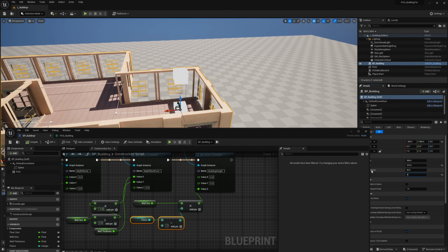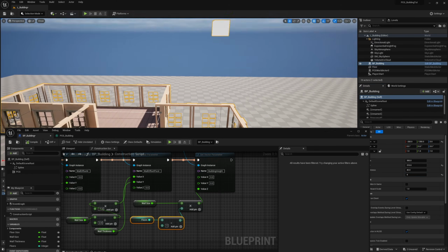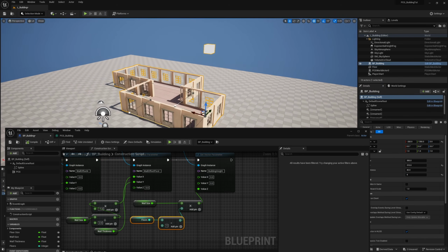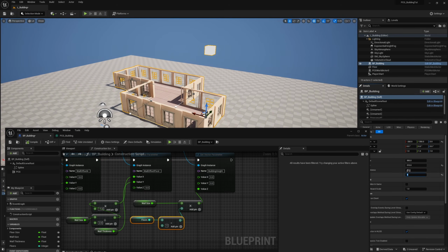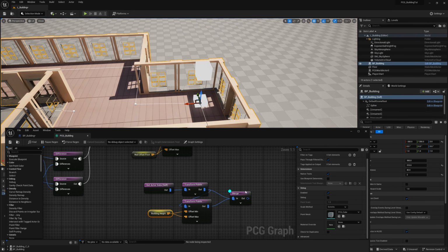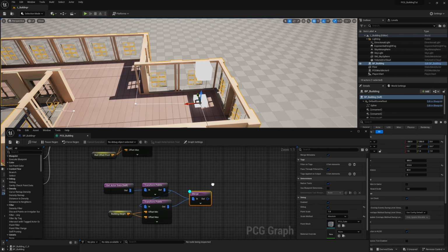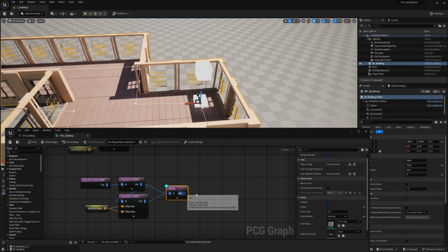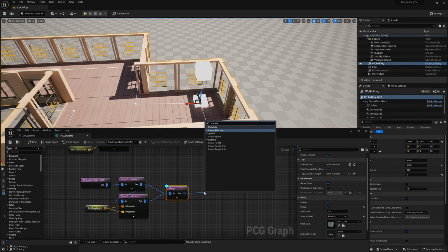So now if I set this to 2, you can see it is adding effectively whatever our wall height is, it is putting that last point wherever it needs to be based on that. Perfect. And from here, we're going to create a spline based on these 2 points. Now that's a reason why we have this merge node. These points need to be merged as one effectively graph. And then from here, you can say create spline.